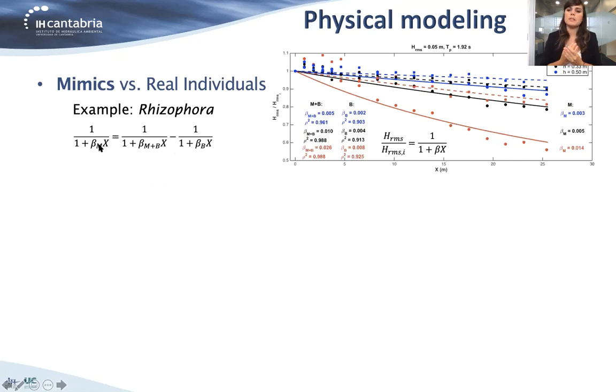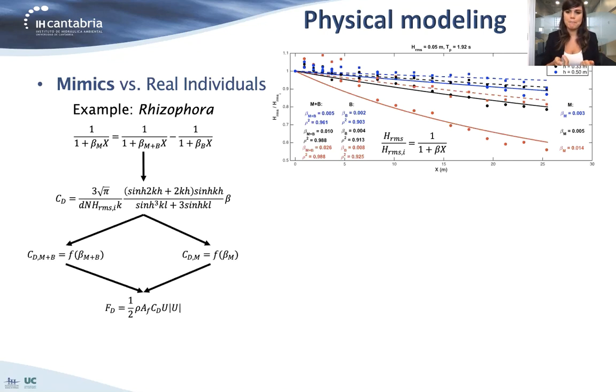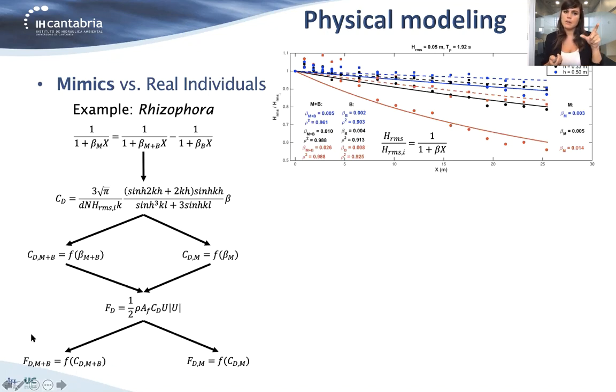One question that we wanted to answer was, can we estimate the drag force, the most commonly used force in numerical models, from wave decay? Following analytical formulations, as shown in the screen, this drag force was computed for both cases, considering the beta coefficient directly obtained from the flume full of mangroves and the one after subtracting the walls and bottom friction of our facility.